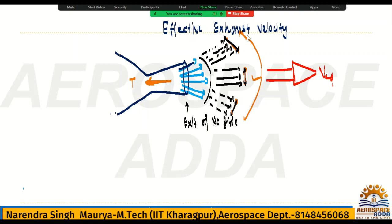So that's the reason for the very common word we use for the rocket engine: thrust vectoring. I hope you all understood why we require the resultant velocity. To get maximum utilization of the exhaust velocity, to get maximum or optimum thrust, we have to find the effective exhaust velocity. This is what I have explained here with the diagram.